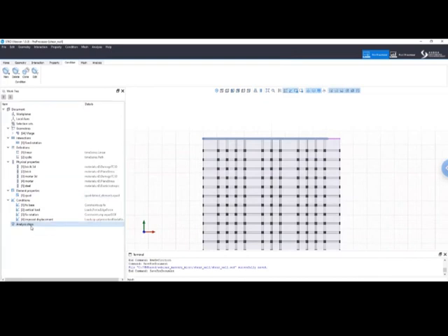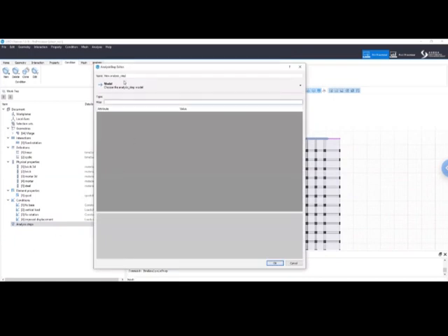So the first thing that I want to do here is to assign boundary conditions. Is to actually apply boundary condition. So the first boundary condition that we want to apply are the fixed constraint and the kinematic constraint for the top beam. So let's call these add conditions. So we go under model, we go under patterns because condition and loads should be added as patterns. So in this case, we want to add a pattern, otherwise we can remove a pattern. In this case, we want to add it, and we want to add a constraint pattern.